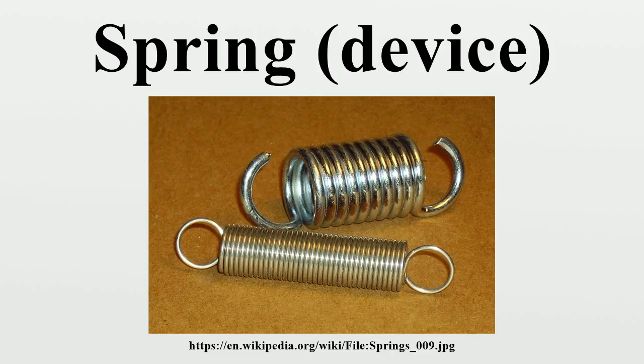A zero-length spring can be attached to a mass on a hinged boom in such a way that the force on the mass is almost exactly balanced by the vertical component of the force from the spring, whatever the position of the boom. This creates a horizontal pendulum with very long oscillation period.